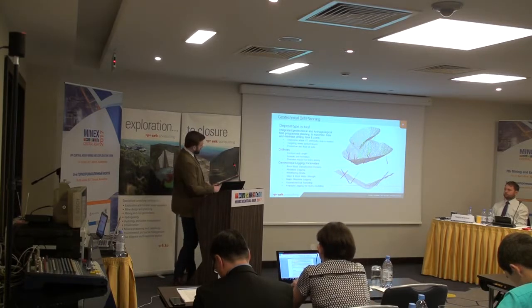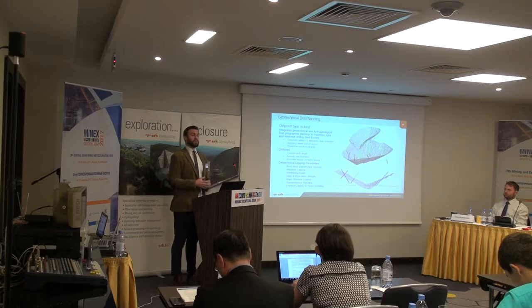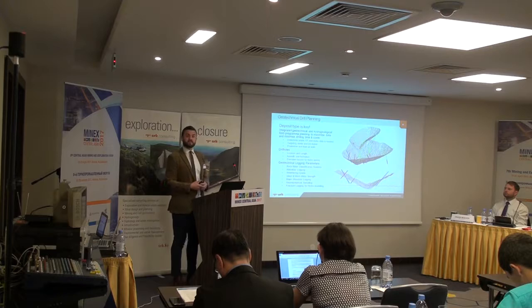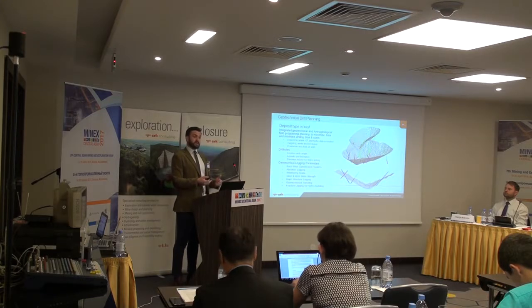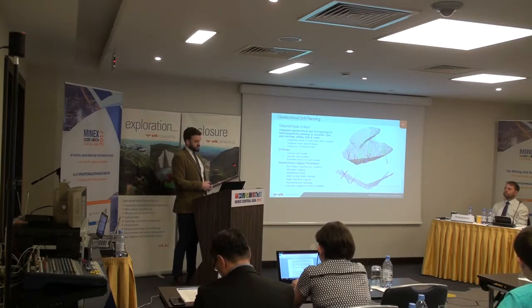And as we said, for the drill holes, you need to think about the location and length. For instance, for a resource drilling program, you might be just targeting the mineralisation. Whereas if you're going to save money and cost and time, why don't you drill the hole an extra 20 metres into the waste material, and then you have a geotechnical hole as well as a resource hole.